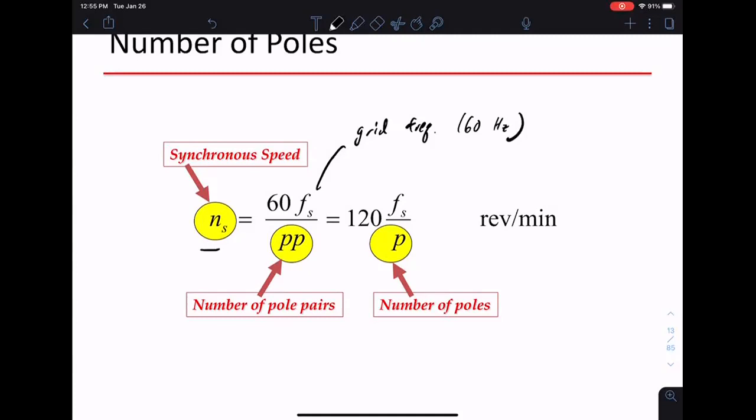Would you stop powering a set of poles? No, because assuming balanced three phase, it's very hard to stop power going somewhere. So this actually is highly non-trivial, to speed up the synchronous speed. You probably have to do it, in the old days, using gearboxes. Nowadays we have electronics. So speeding up is not easy. But by adding poles, we can slow it down.